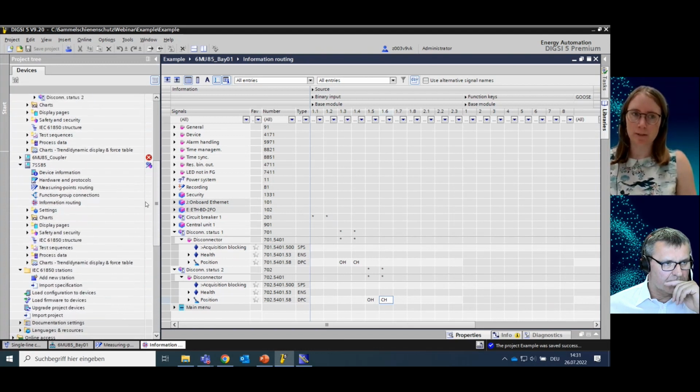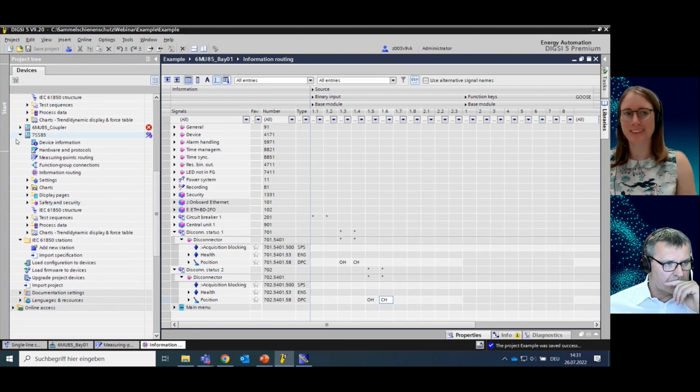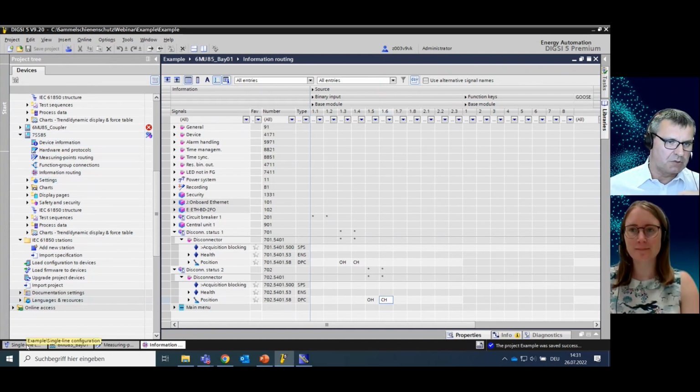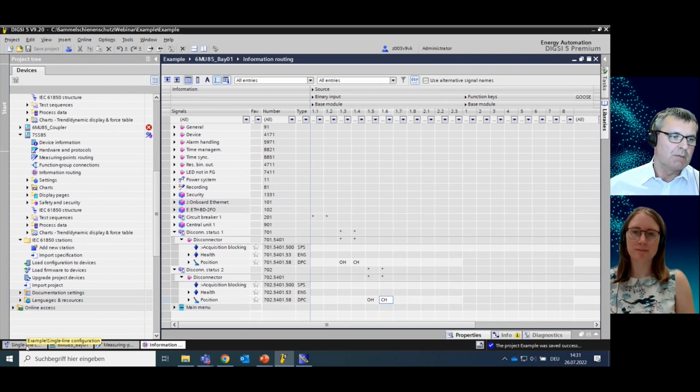Now I will come to the also most important changes for the central unit. Of course, you should not forget to adapt the settings of the current thresholds for the circuit breaker failure protection, to route the start signal of the circuit breaker failure protection and so on. But I think it's fine for today. I think we want to demonstrate really the special things for distributed busbar protection.